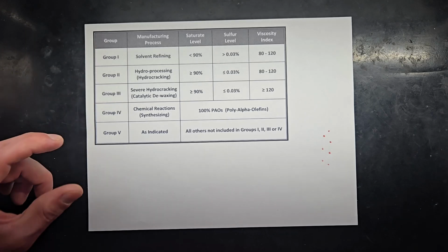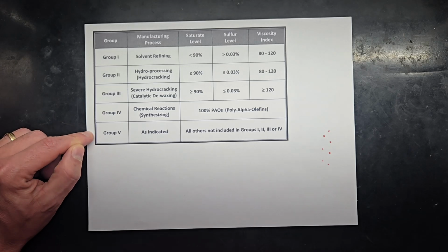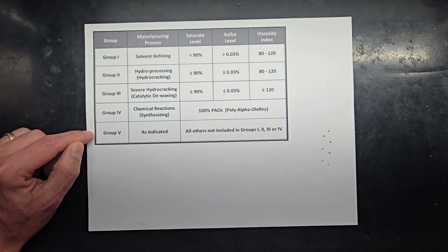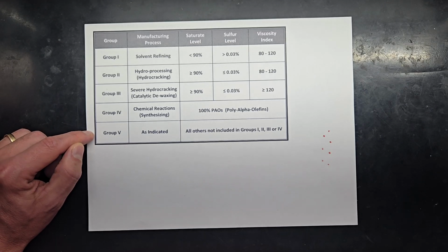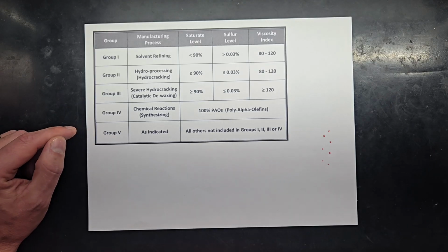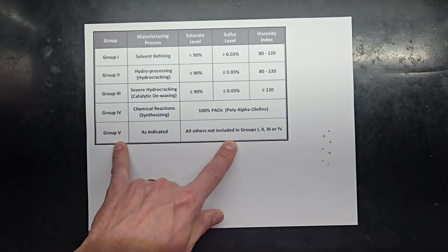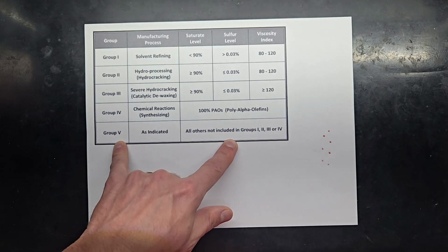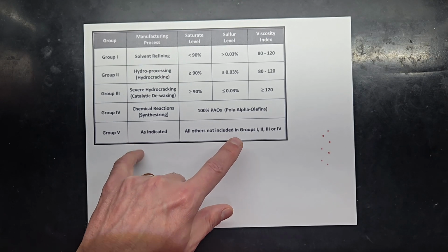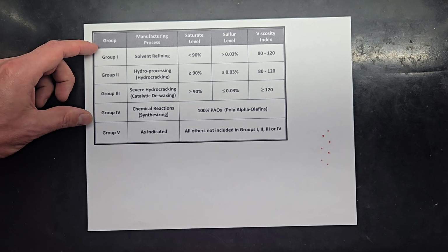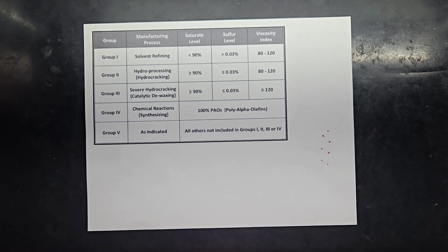But a naphthene-based oil does have a place, and it falls underneath a Group 5 base oil. We also have our esters, our PAGs, our silicon oils, as well as vegetable oils in this Group 5. So Group 5s are really more of a catch-all, versus our Groups 1 through 4, which define a little bit more about the structure.